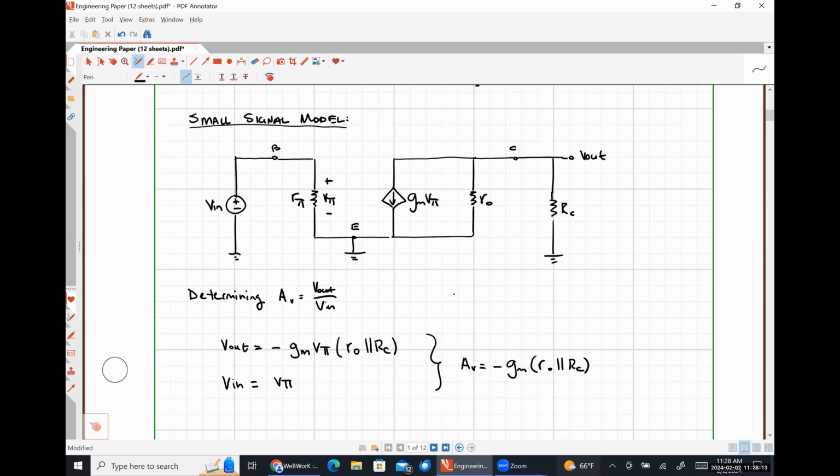So we're going to do this because this one is so easy, effectively by inspection, right? So I'm going to treat my input voltage as if it were a test voltage source. And my input resistance is then just going to be the ratio of this voltage V in to this current I in. What should that be?